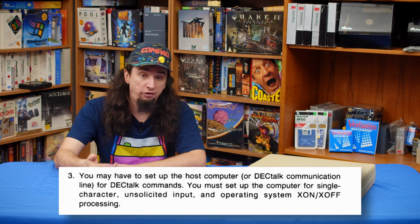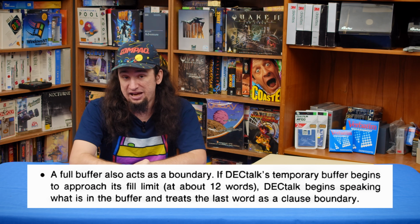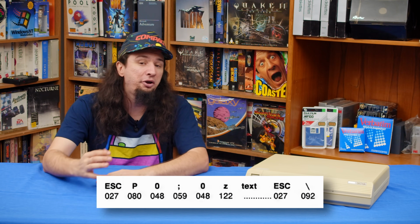Primarily, it supports software flow control, which is critically important because the input buffer is very small, only 12 words according to the manual, but also because the host port supports additional commands. There are a bunch of these that we don't have time to get into because of how feature-packed this thing is, but using an escape character prefix with a command string, you can access even more features. With this, we can fully control the DECtalk as a programmable phone. Let's test this by using a command to dial a phone number to the other line and send it a message.